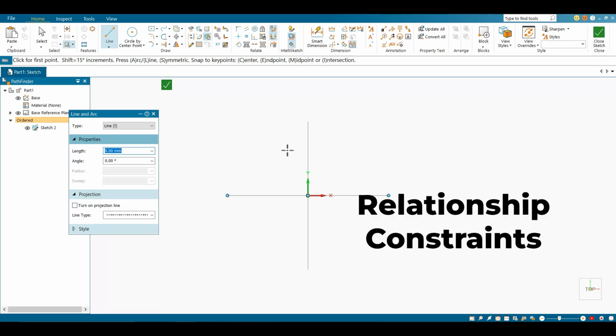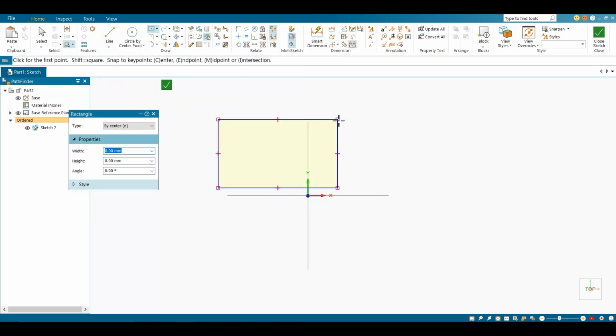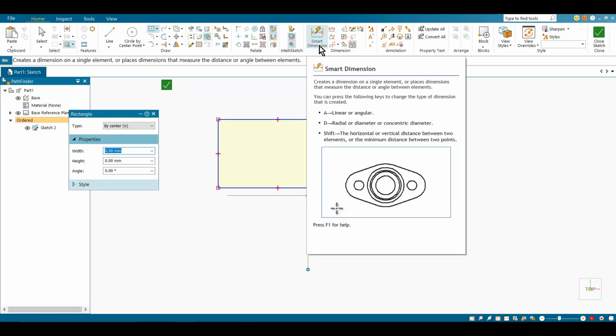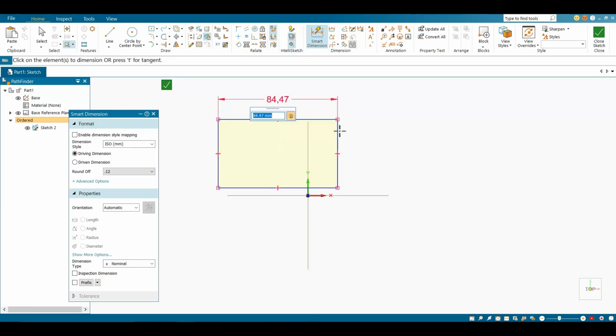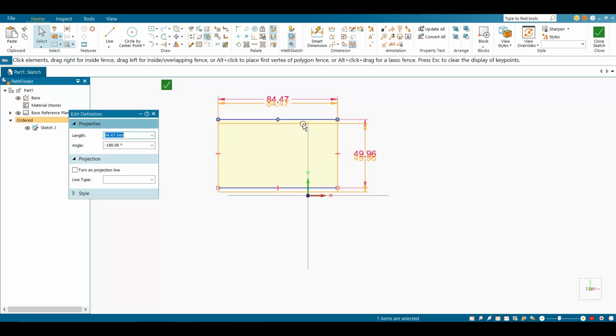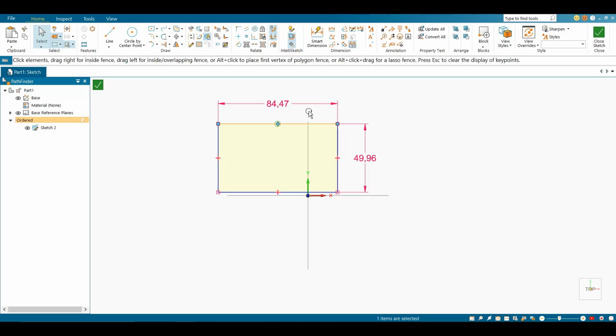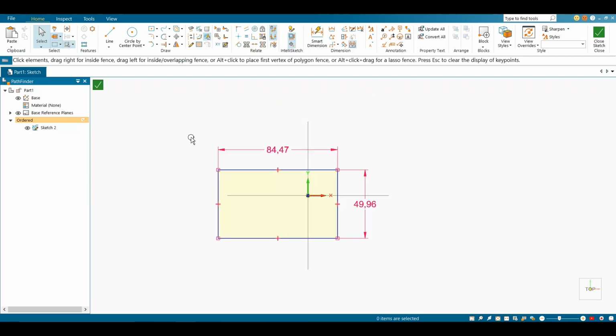You have a basic idea that in any CAD, after finishing your drawing, you will need to provide all the required dimensions and constraints to make it fully constrained. For example, if I have given some dimensions to this sketch, but it is still not fully constrained, and some user comes here and edits any dimension or directly moves this drawing anywhere, then that particular sketch will be disturbed throughout. So this is not best practice. In any CAD, we first need to fully constrain the object.